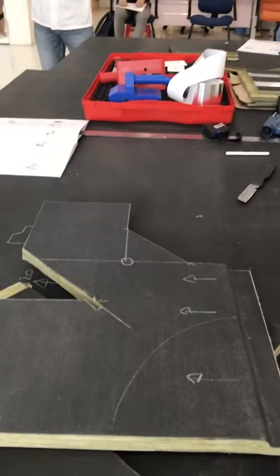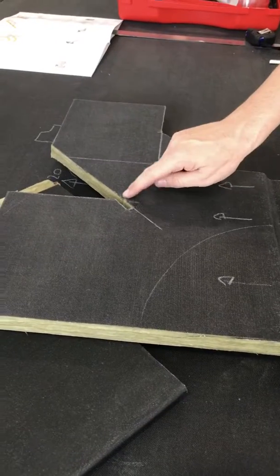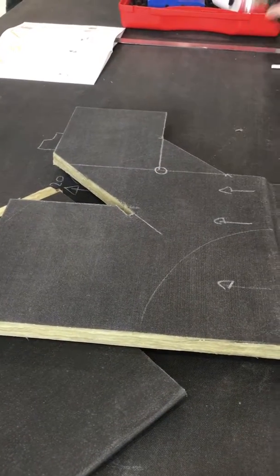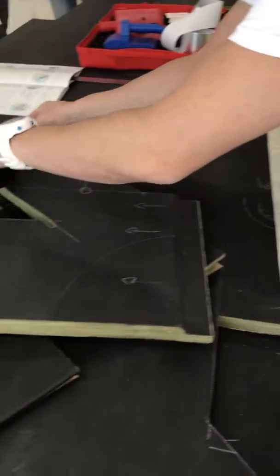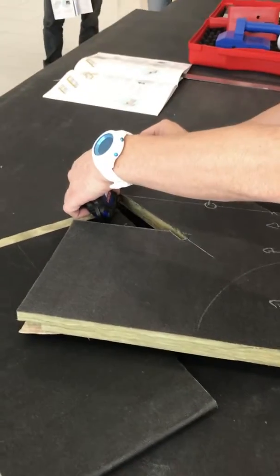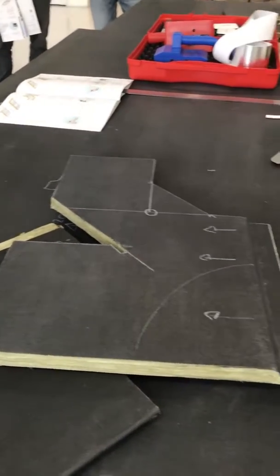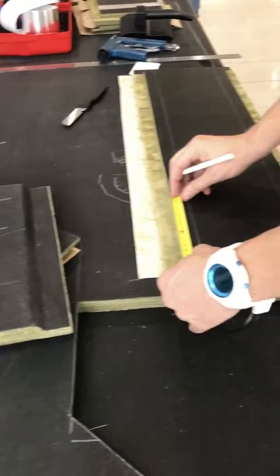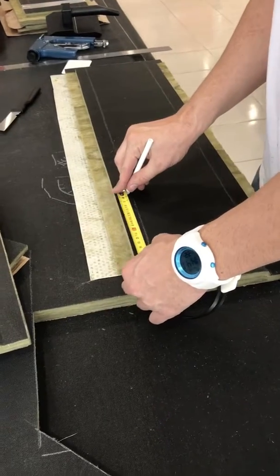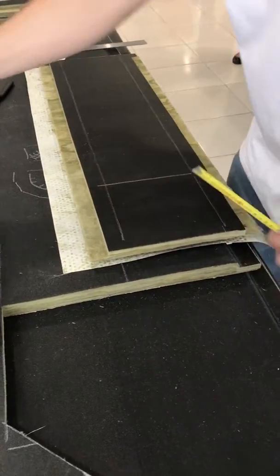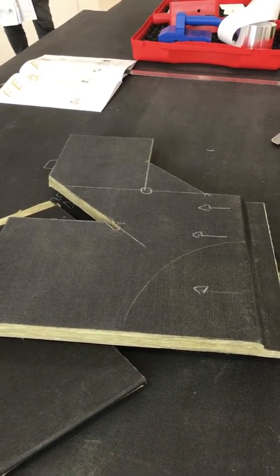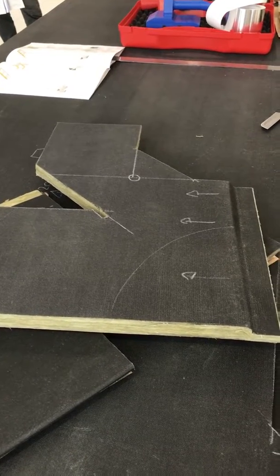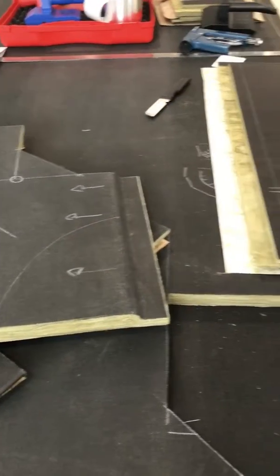Then we were doing this lateral wall. See it? We have done the male, and from the male up to the corner we have 16.5. Okay? Then I'm going to draw 16.5. And here that's an external corner, that means a groove of 1 centimeter. Then at 1 centimeter more, or 17.5 from the beginning, a second line.